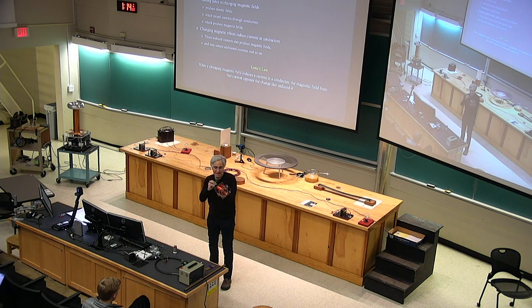When I push this magnet in there like that, current flows, it becomes magnetic, it fights the entry of the magnet into the coil. That sucks energy out of me, it does negative work on me, and that pays for the energy of lighting a light bulb. When I try to yank the magnet back out of the coil, it fights me again. That's Lenz's law in action.